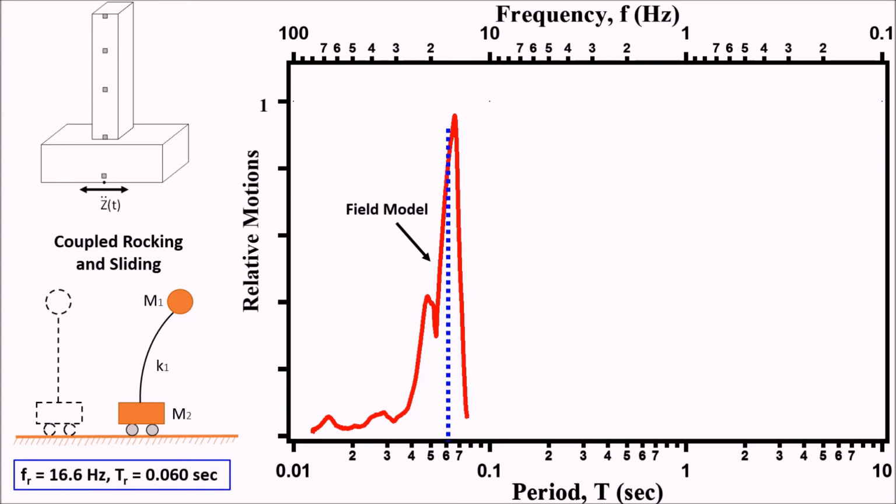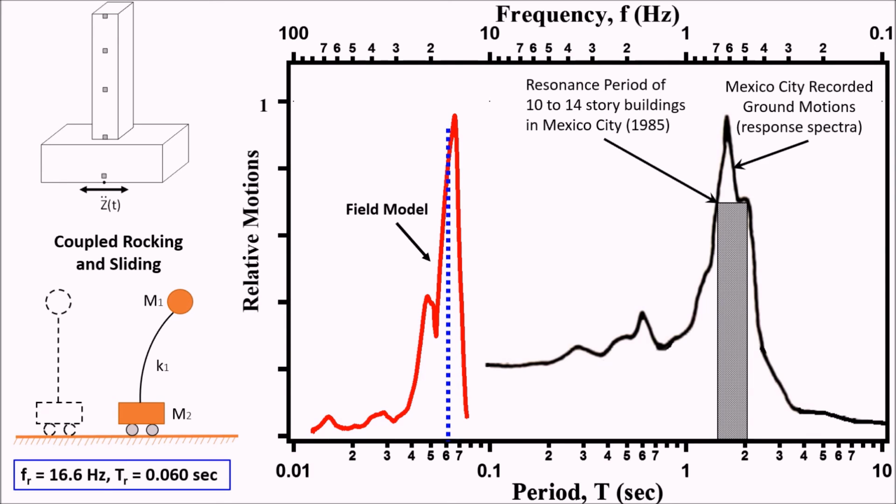In summary, in practice today, the geotechnical engineer provides the response spectra of a site to the structural engineer, who will ensure that the building does not have resonance in the frequency range excited by the earthquake, or is built to withstand the shaking.